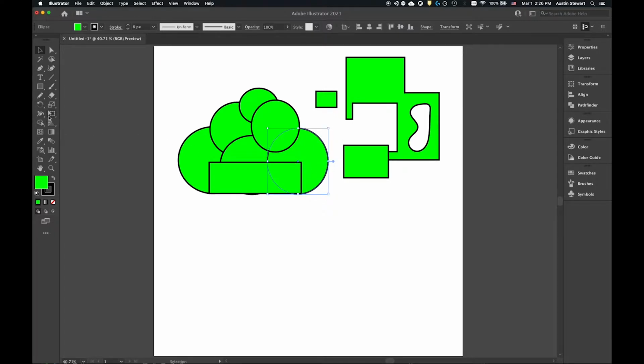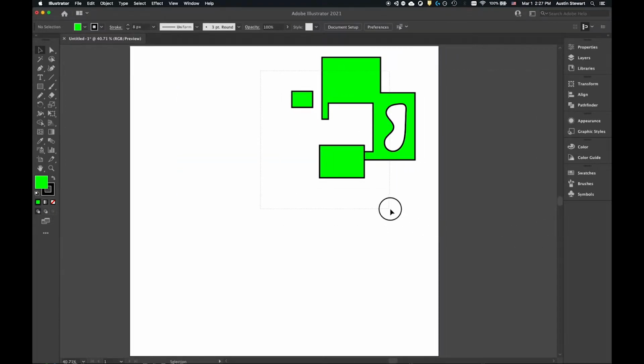All right, but I've got all of those points, so now I just grab the Shape Builder tool. First, I select everything that I want to build together, and then I use Shift and M, and I can just click and drag to connect all of these shapes. Now, note this might be a little bit crazy use for it because there's so many different pieces in there. But I can do that, and then I get this one contiguous thing, and it looks like I missed a little bit down there at the bottom, but that's fine. Now I have this contiguous, flatly colored cloud that I made very, very quickly. Okay, so I'm going to go ahead and delete that, and delete this.